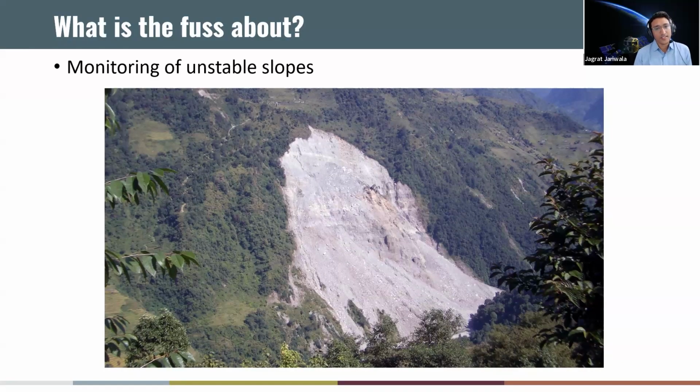And then I've used InSAR for monitoring slopes and use it as a force multiplier for other conventional monitoring, spatially as well as temporally. Get more dense estimates spatially, and can get more frequent estimates and reduce the cost of your conventional monitoring.